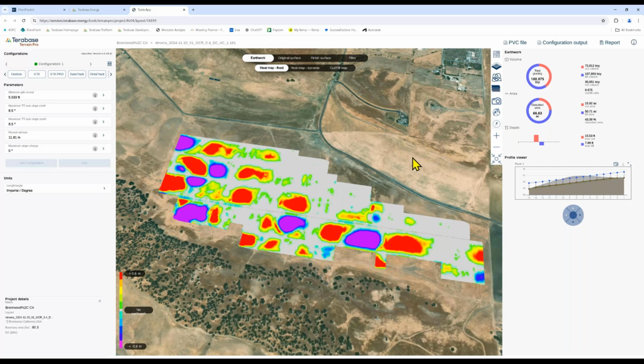And you might be wondering, well, where did you get your elevation data from, right? So if we look at the bar on the right side, we can see what the elevation source data was. And in this case, it's from the USGS. The site is in the US. It's a 1 meter resolution, and it's from their 3DEP program, which is their program that they are currently working on to collect LiDAR information for the United States.